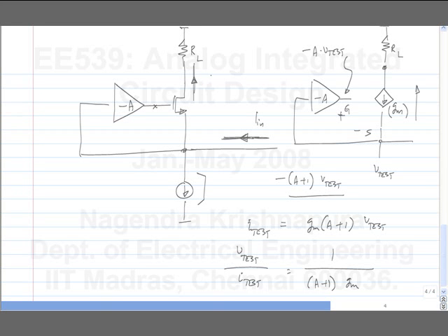The idea here is to make these amplifier stages which are biased at a constant current, so that the variation in gm with process and temperature is small. And if the variation in gm is small, the variation in small signal characteristics of the amplifier will also be small, smaller than if you bias it at a constant VGS.